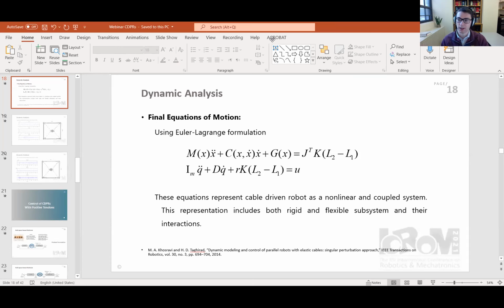I was wondering, either through the theory or experience, do you see any issues or need for certain types of excitation in the dynamics to be able to estimate those parameters? So like in adaptive control, we typically have this persistence of excitation condition where we have to have things changing to be able to actually converge our estimates of the parameters. Is that something that you see here?